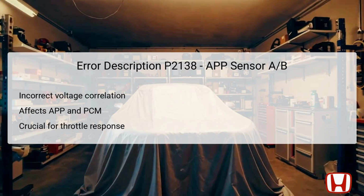DTC P2138 indicates an incorrect voltage correlation between the APP sensor A and APP sensor B, which are critical components that relay the position of the accelerator pedal to the PCM. These sensors are located on the accelerator pedal assembly, which is mounted in the vehicle's footwell. When the driver presses the accelerator, the APP sensors generate a voltage that is sent to the PCM, allowing it to adjust engine throttle accordingly.